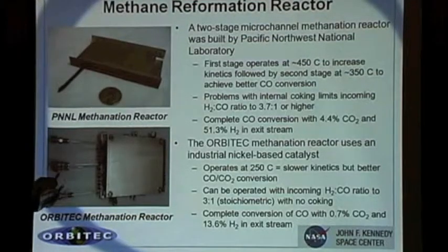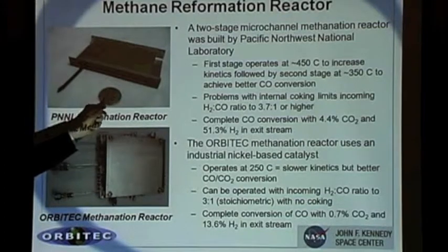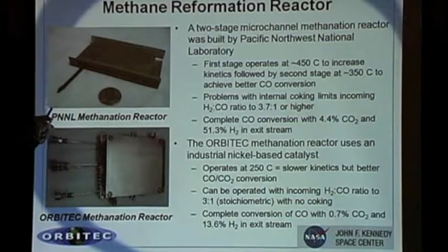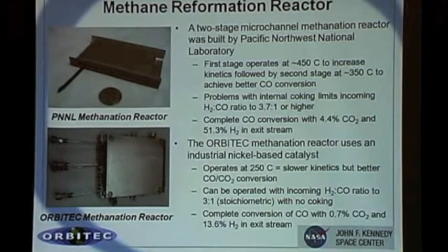please. I mentioned this reaction. It's also called a methane reformation reactor. Pacific Northwest Laboratories has built a unit that was tested, and then Orbitec built its own version. It turns out we used the Orbitec version because we ran into some issues with this one. This is a micro-channel reactor. It uses very small amounts of catalyst to be very lightweight, but it's also very touchy because carbon monoxide can disproportionate into carbon and carbon dioxide, and the carbon will clog up your reactor. This one runs at a lower temperature, so the carbon monoxide does not disproportionate, but it's still fairly